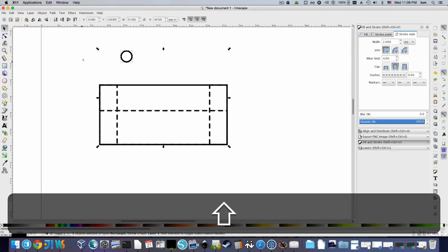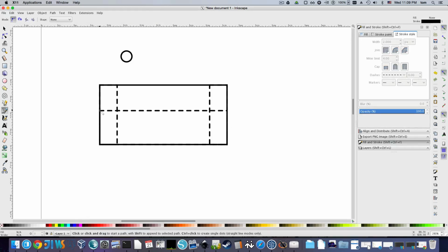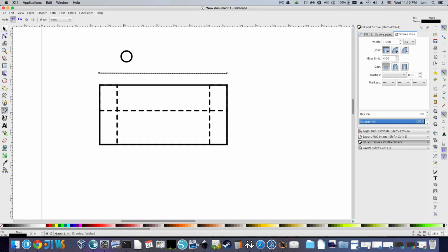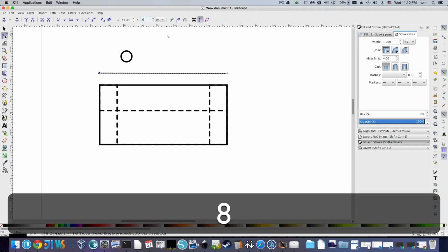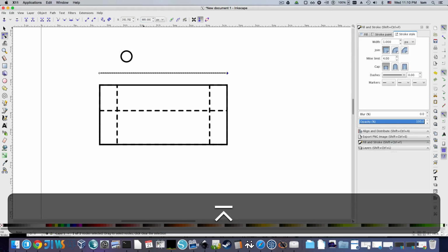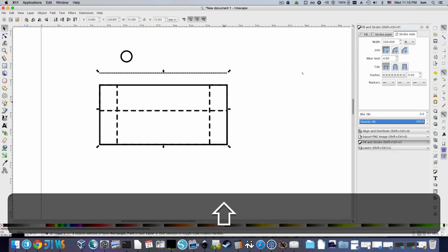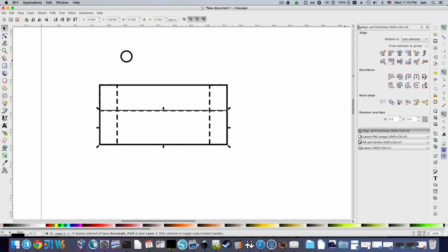And then we can, alright, here's one of the issues that we have to deal with here. You can't center an object on the side of a box. So here's one little cheat. Make a straight line, relatively. And we can make sure that it's straight by going in here and exaggerating the y coordinates on each of the points. And that assures that the line is straight. And then we can line it up to the top of this edge.